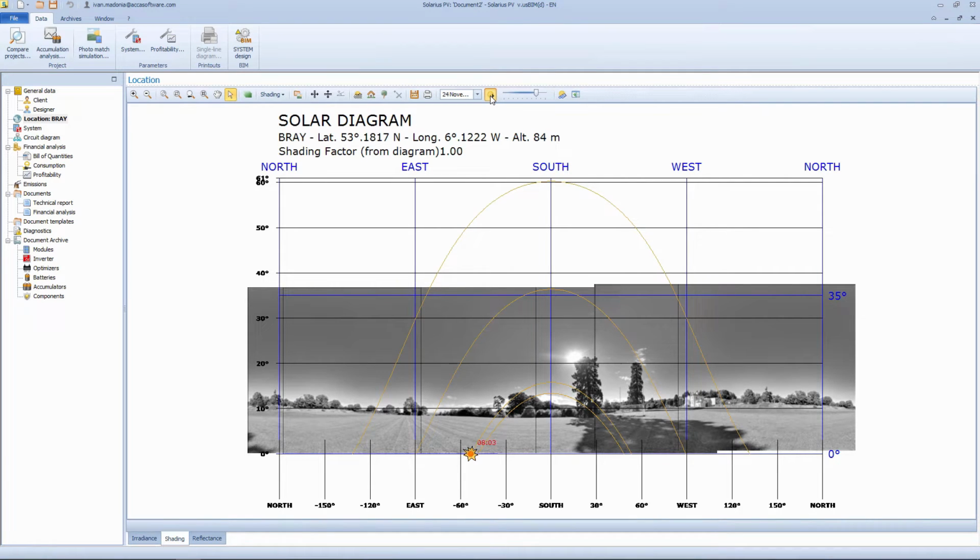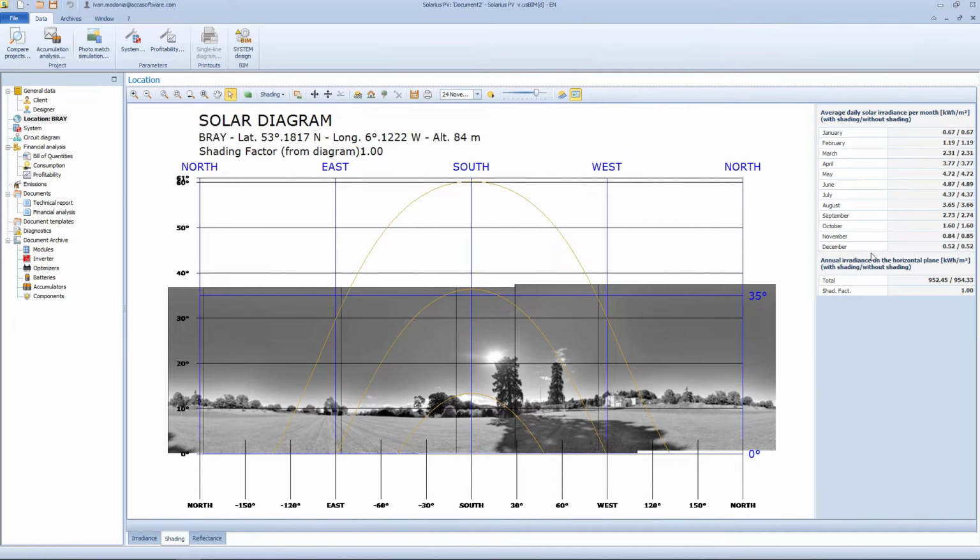The software calculates the system's efficiency based on azimuth and tilt values for that specific location. It highlights the importance of an optimized module positioning, considering factors such as hills, mountains, trees, and buildings that may influence solar radiation. You can define the shading factors and seasonal shading percentages. Here we will apply some modifications, keeping an eye on the shading factor to see how its value will change.